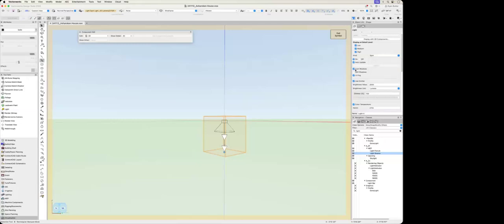You could turn off shadows or not. You could also change the brightness and the dimmer and the color temperature. Now these three areas over here are very important. So if I wanted to make this a little bit lighter, maybe 4,000 lumens, and then also change the temperature to 3,000, that would change how the light looks. So let's take a look at it.